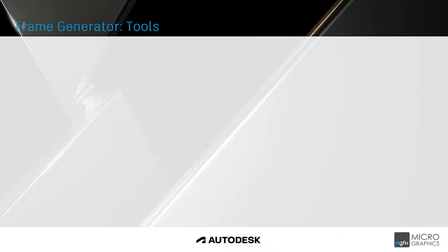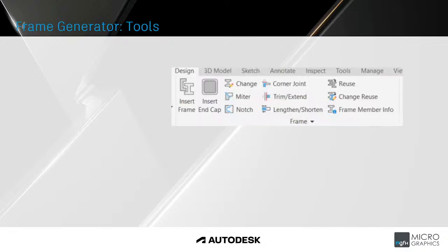So let's look at some of the frame generator tools that are available. As you can see, you've got your insert frame, insert end cap, your change, your miter, your notch, your corner joints. So these are some of the tools you get. So first we've got the insert end cap. This places end caps on the selected frame members.